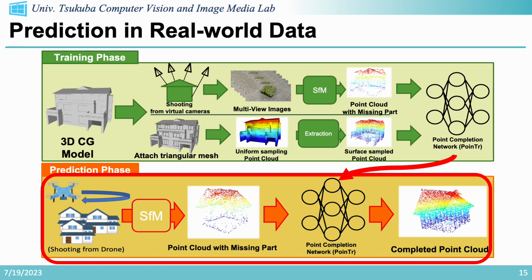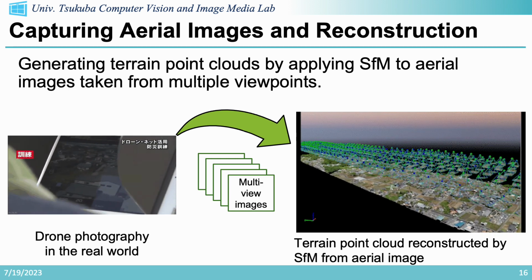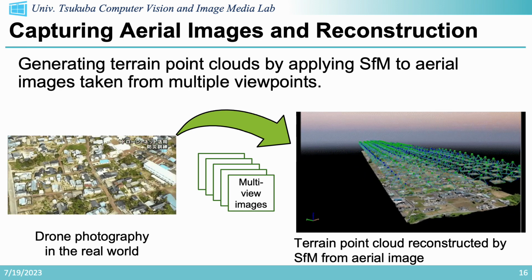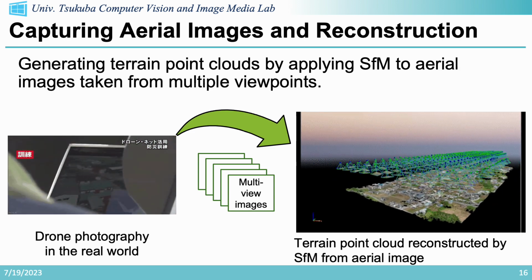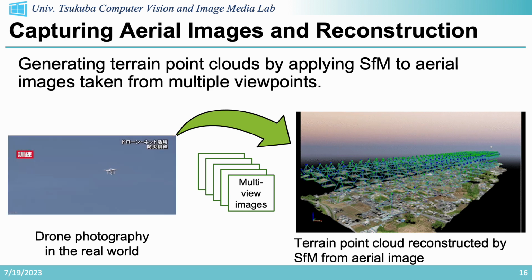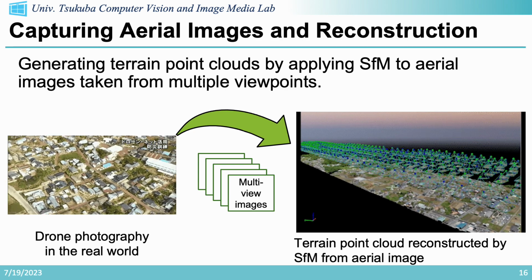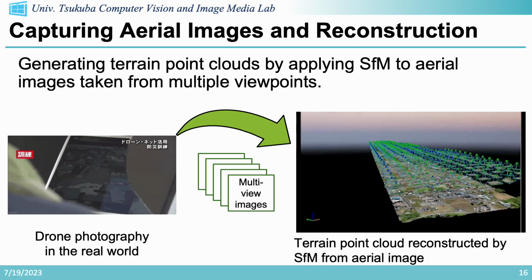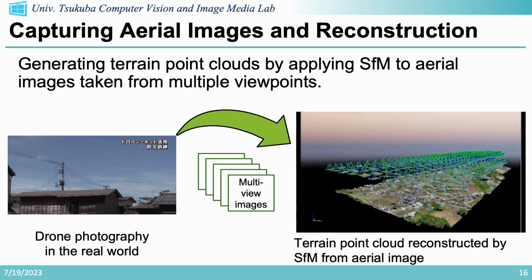Finally, I will talk about the prediction results on real-world data. In order to measure the utility of the method for real-world data, SfM is applied to aerial images taken by drone, and point completion is performed on the reconstructed point cloud. We shot the drone images from an altitude of about 100 meters and applied SfM to the obtained images to generate a terrain point cloud, as shown in the figure on the right.